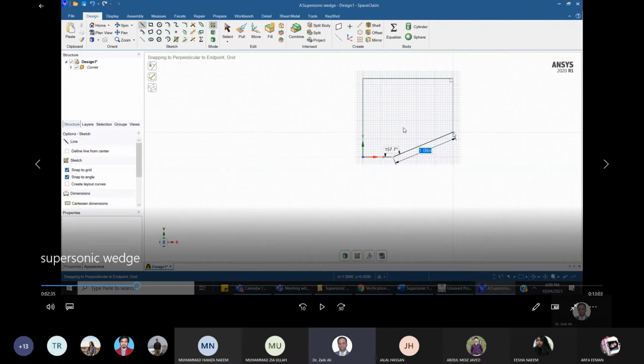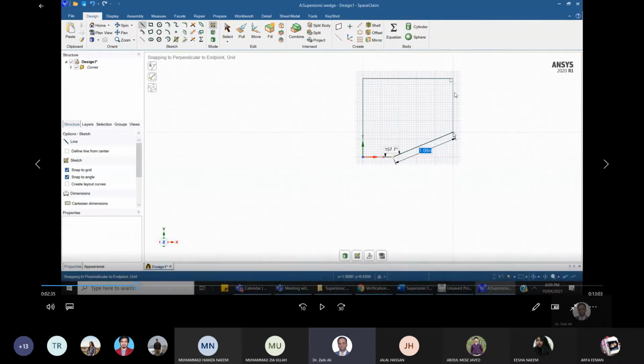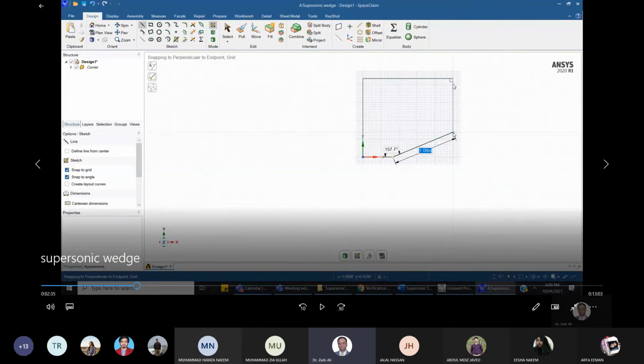And then also you want to make sure that you are drawing it vertically, so there should be this right angle symbol visible as well. Only in that case will it ensure that this point over here is at 90 degrees to this. So keep scrolling it down to 165 and also make sure that you are drawing it vertically so that this right angle symbol is visible.